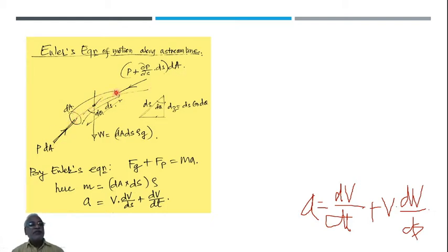A very small portion of length ds is considered. There is a stream tube considered with cross-sectional area dA. Here also it will be dA only, though it is shown with a slightly different size, it is a very small magnitude, exaggerated in scale. It is a tube with the same diameter, so dA over here also.